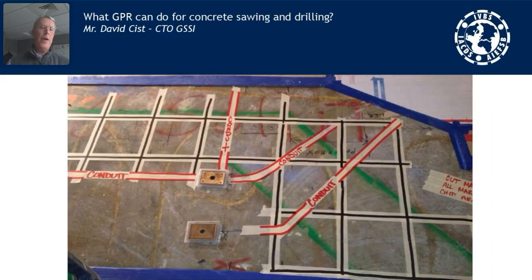Typically, you have problems like this, which are easily solved. You can mark out and map out a duct, a track that you want to cut. You can see, for example, you know that there is going to be a conduit coming from these junction boxes. You want to cut this trench, and you don't want to hit the conduit. So this green line would be your cut line. The green line would show you that you can cut and remove material up until the red conduits, and then you might want to go more slowly and dig by hand around the conduits to avoid cutting them.